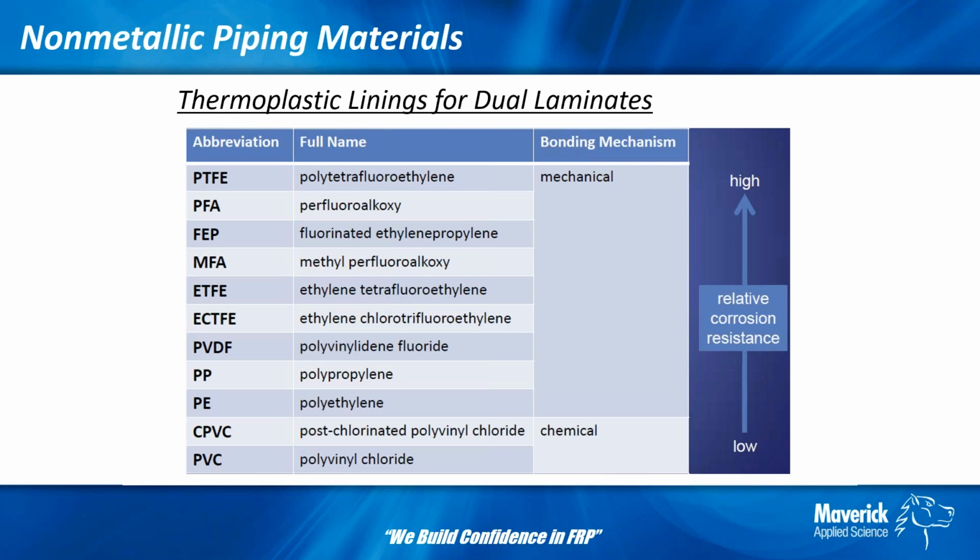When we're looking at thermoplastics, I should also mention that it's not just about chemical resistance, it's also about permeation. All of these polymers are a little bit different. Some of them are harder, like CPVC is a very, very hard polymer, and ECTFE is another one that's very hard. But a PFA or FEP is a fluoropolymer on the high end, but it's also not as hard and more porous than some of the other materials. So we also want to look at permeation based on that specific chemistry. When we're evaluating linings or even just direct thermoplastics, we want to consider our chemical resistance under the operating conditions, as well as the permeation for that specific material in that chemistry.